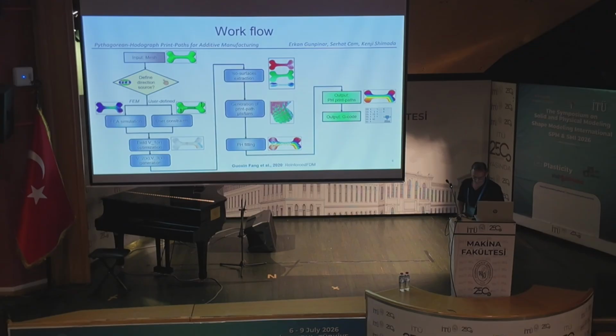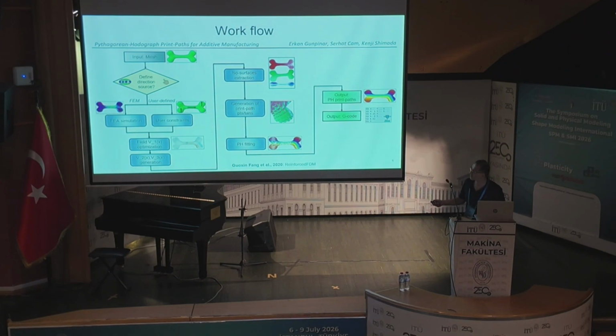So here's the proposed workflow. We begin with a tetrahedral mesh. Of course, we can use hex meshes as well. And then we define a guiding vector field. It can be either coming from FEM simulations or it can even be user-defined. And we optimize this field.